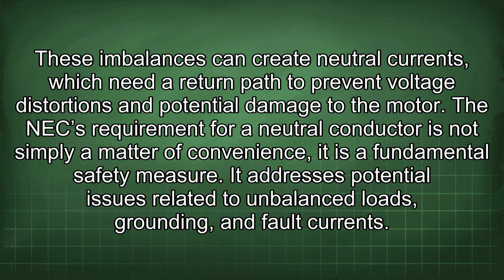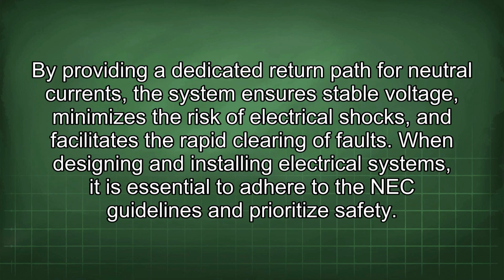The NEC requirement for a neutral conductor is not simply a matter of convenience, it is a fundamental safety measure. It addresses potential issues related to unbalanced loads, grounding, and fault currents. By providing a dedicated return path for neutral currents, the system ensures stable voltage, minimizes the risk of electrical shocks, and facilitates the rapid clearing of faults.